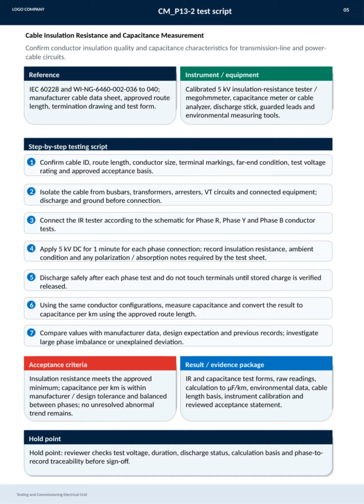All results, including raw data, calculations, environmental factors, cable length basis, instrument calibration, and reviewed acceptance statements, form part of the evidence package. Finally, before sign-off, the review includes a hold point to verify the test voltage, duration, discharge status, calculation basis, and traceability of phase-to-record data, ensuring full compliance and reliability.